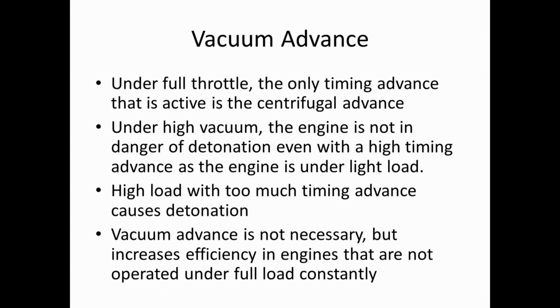So your vacuum advance isn't really necessary. You don't really see it in racing applications, marine applications, stuff like that, because in those applications the engine's usually operated under full load most of the time, making vacuum advance essentially useless. But in an engine that's doing a lot of highway cruising, stuff like that, vacuum advance actually increases your fuel efficiency and your engine efficiency substantially.